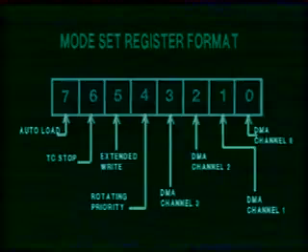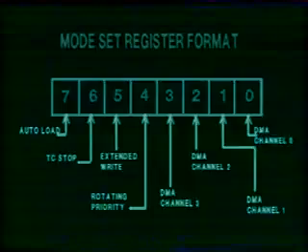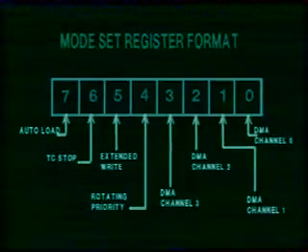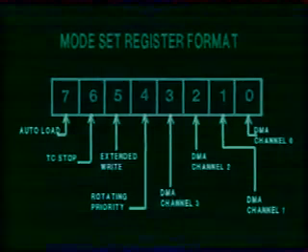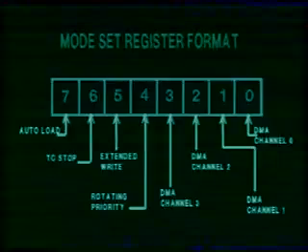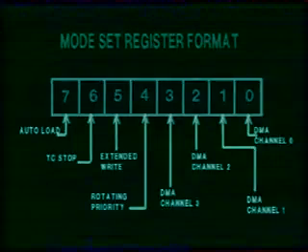Bit D4 enables rotating priority. Bit D5 enables extended write. Bit D6 enables TC stop. Bit D7 enables auto load.